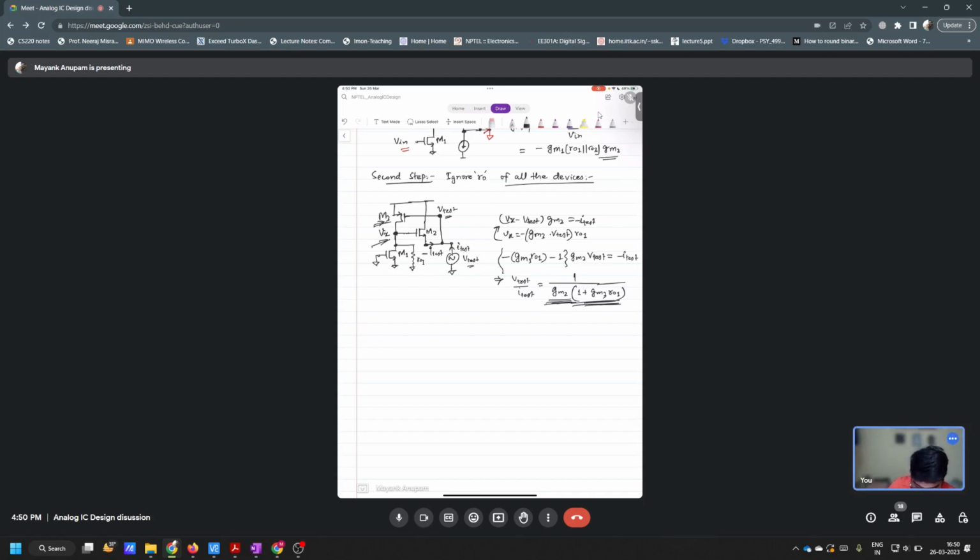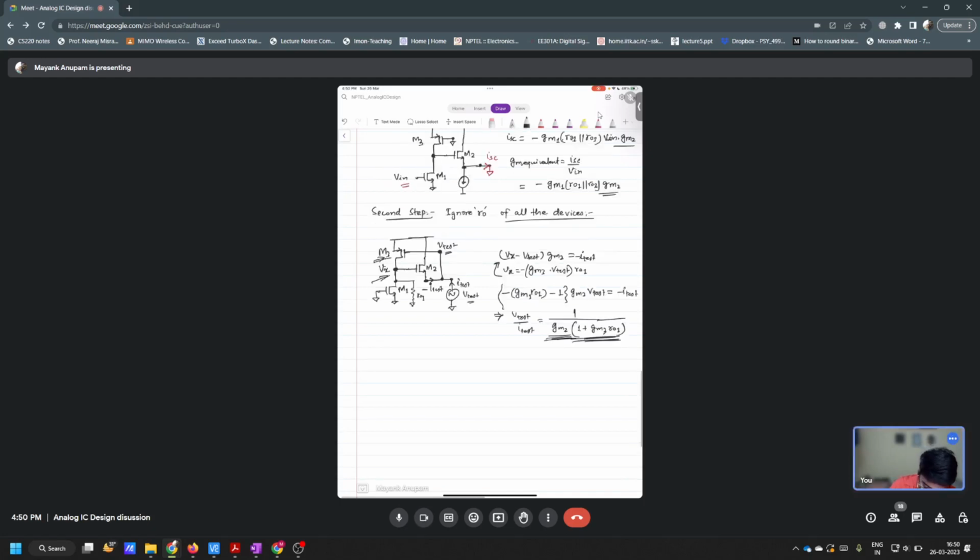Tell me. Negative, negative. How? Why do you say that? Sir, if we increase V out, like V test, then the gate voltage of M3 is increasing, and the output at the drain of M3 is decreasing.